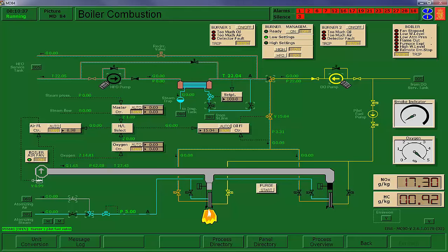Okay. Now, once we have a good fire, we want to make sure that we don't smoke. And part of that is don't go below 2% oxygen here. You can read oxygen here, but also here. That's the boiler flue gas oxygen content. But this firing rate would give us steam within about 30 minutes, and we can't have that. So we have to drop that down.